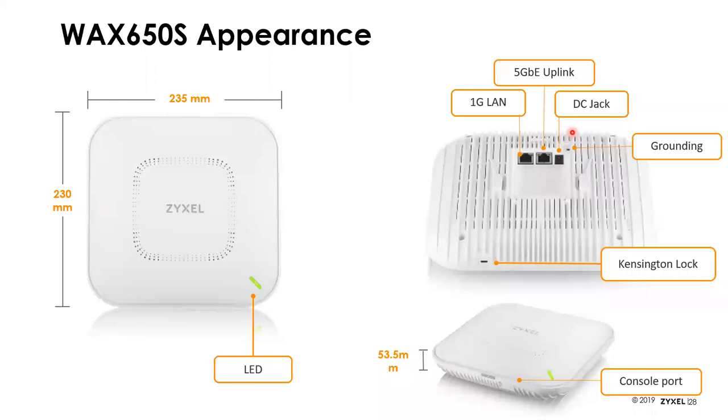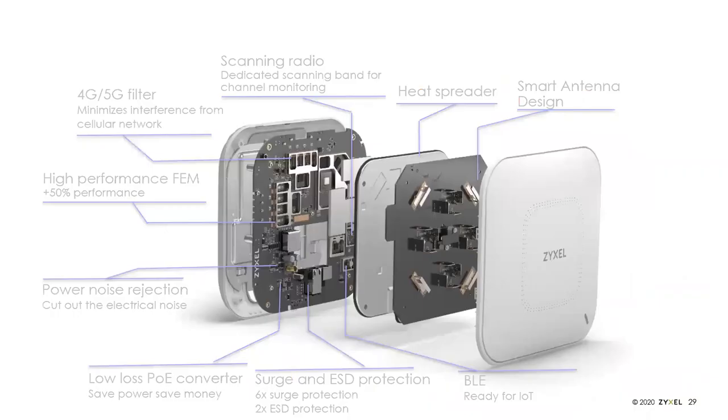If you plug this in and use it on an 802.3 AT PoE device, it will still run, but it'll only use 2 spatial streams. So you're basically cutting your Wi-Fi throughput in half if you're not hooking it up to a BT PoE device.